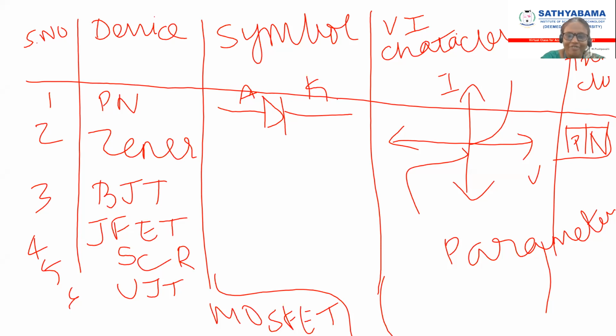When you move on to JFET, reverse voltage rating, yeah, good. In JFET you have to write about transconductance, and amplification factor, you have to explain. In JFET, what are the other terms we have discussed? Is there any formula we have discussed in JFET? In transfer characteristics, do you remember? ID equals IDSS, drain saturation current, times 1 minus VGS by VP, the whole square.